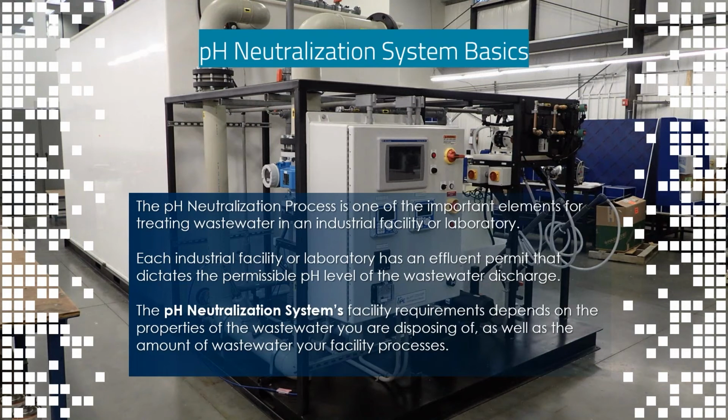And because of the chemicals involved and the corrosive nature of these, they can be hard to just put outside. If you put them outside, you obviously need to heat trace them if you're in a cold environment. If you're using things like caustic soda in them, it's not very practical since you have to maintain a fairly high temperature for its use. So it makes a really good candidate for a pH treatment system.